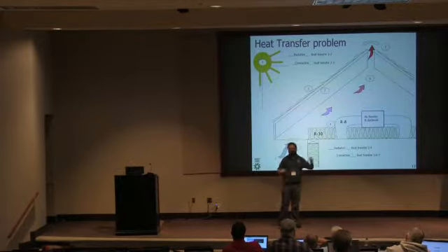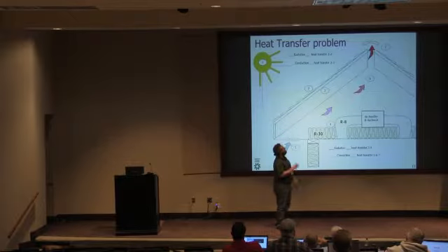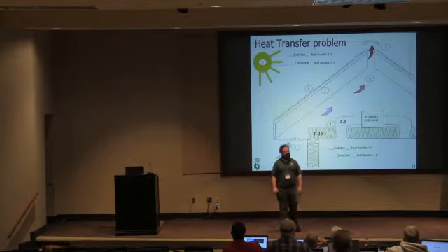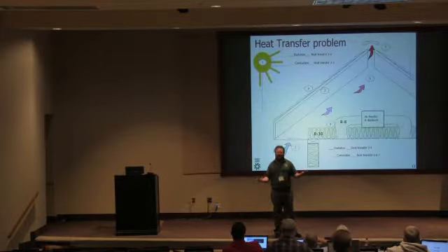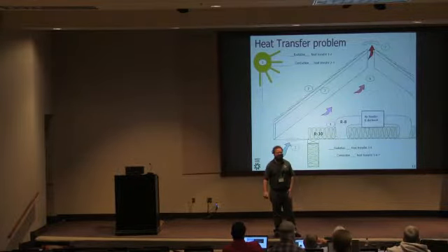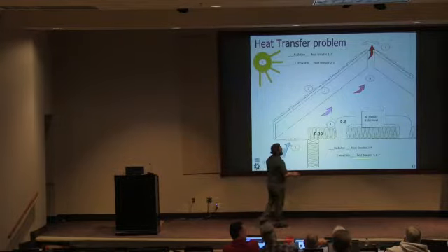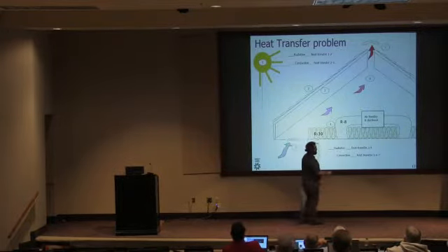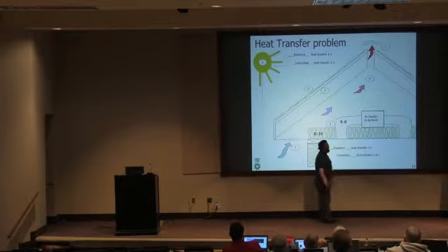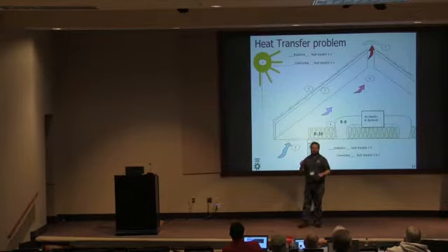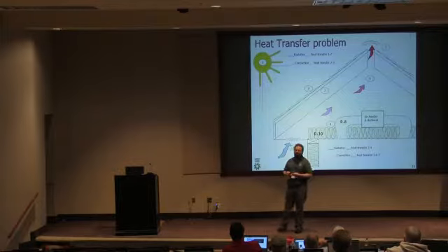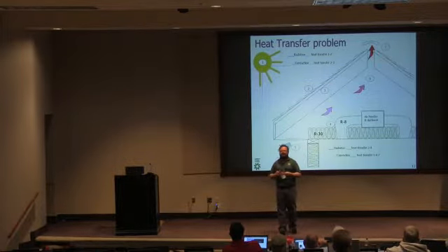convective air. And then sometimes you see people do silly things like, y'all ever seen somebody put a power attic ventilator up there? Will that cool the attic? Oh, absolutely it'll cool the attic. What's it going to cool the attic with? The second floor conditioned air. That's exactly right. It'll help. So now you're basically depressurizing your house by depressurizing your attic. You're sucking conditioned air out of your home and into your attic. You're wasting energy. You're setting up a bad air quality situation with a house now under negative pressure.